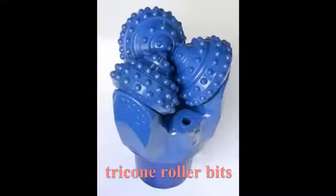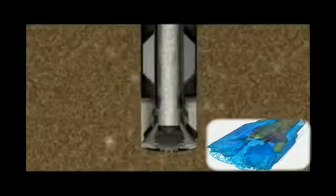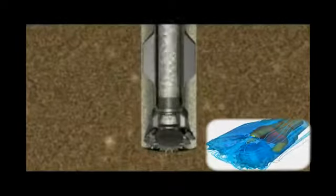Tricone roller bits are the most commonly used bits. A clockwork rotation of the drill string causes the 3 roller cones to also rotate, bringing successive teeth to grind vertically at the bottom of the hole. With the weight concentrating at the point of the teeth, the rotating bit crushes the rock. The debris from these cuttings is then swept away by the mud jetting out of the 3 downward-facing nozzles.